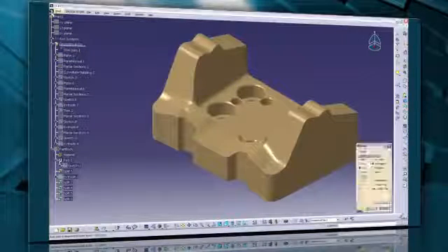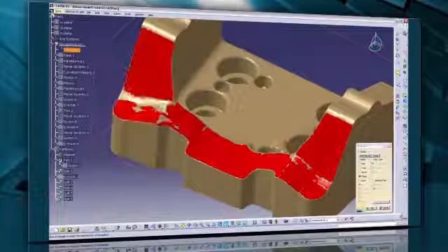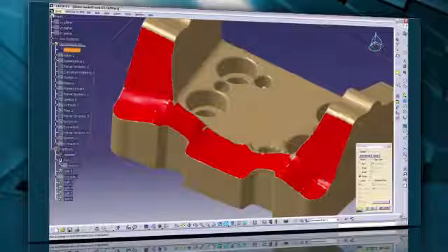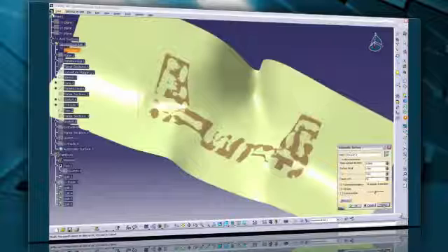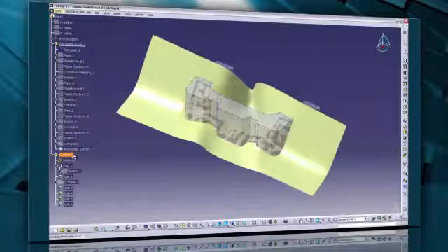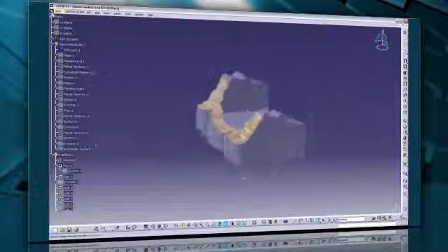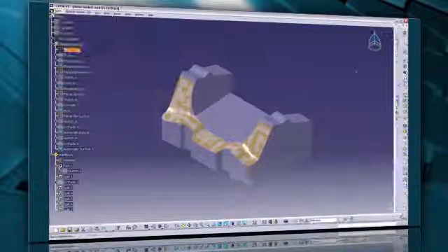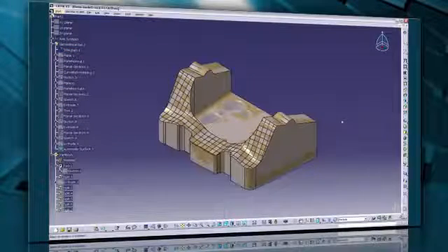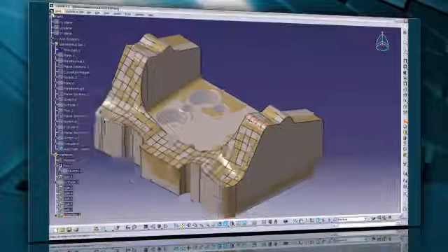For complex surfaces, QSR has tools to reconstruct them by quickly approximating the shape with a brush-like tool or flood selection. The surface does not need to be perfect. Then, using an automatic surface tool in QSR, the resulting unlimited surface is created and is usable as a splitting tool in the part design workbench. After the main surfaces are created, you can use the usual tools of part design for the remaining operations. Easily create missing fillets and add features like holes and pockets.